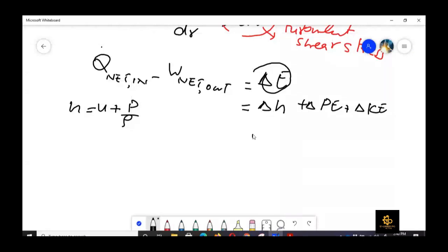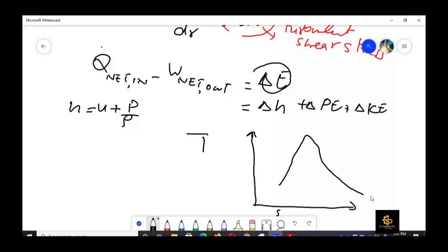In your previous chapter, in your previous semester, if we draw the T-s diagram for that, you may remember there is a bell-shaped curve here, that is the saturation curve. If we draw the cycle here, that is like this. That is the pump work, then we have the boiler, then the superheated region, and then that is the turbine work, and then this is something. So this is ideal, when there is no friction.